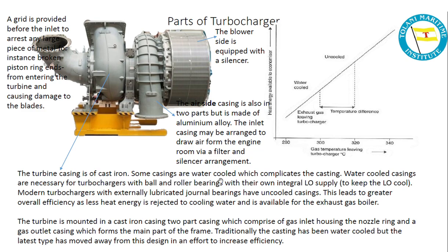Some casings are water cooled, which complicates the casting. Water cooled casings are necessary for turbochargers with ball and roller bearings, with, you remember, inboard and outboard bearings we have already discussed, with their own integral lube oil supply. So here we have its own integral lube oil supply to keep the lube oil cool. Modern turbochargers with externally lubricated journal bearings have uncooled casing. So we have even turbochargers which are uncooled.